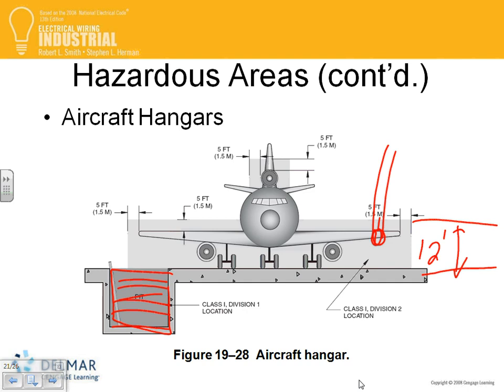Let's say they needed full power up for some reason. They have extra hard cord. You need a cord to work on equipment. They plug it into a GFCI somewhere outside this area, so it doesn't have to be explosion proof. And they use extra hard cord with equipment rated to work on equipment. No arc fault. Just GFCI.